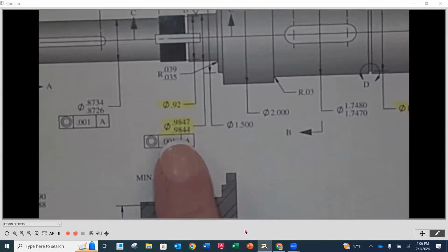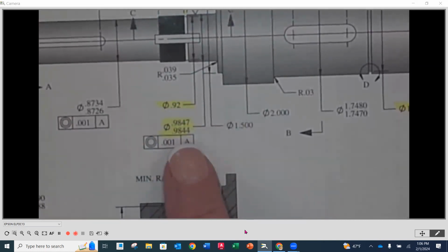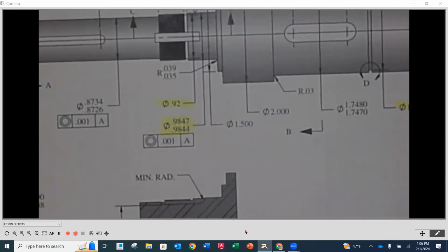If you start having bearings fail early and you say, hey, Fafner, we're having a problem, the first thing they're going to do is say, let me see your drawing. Okay. And if you did not incorporate their tolerances, they're not going to stand behind it. Okay. End of story. So you have to take that, and that's any vendor.